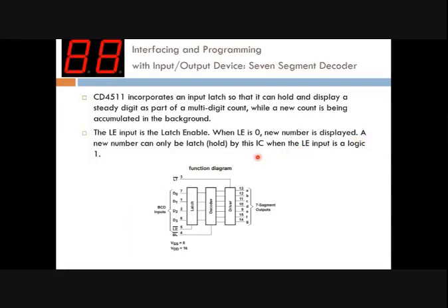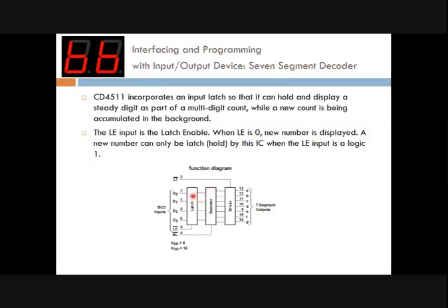After the updating process, you go back to giving LE 1 so that it can hold the value. So if the new value is 2, you turn on by giving 0, then the latch will update to number 2, and then to hold that value, you turn off again by giving 1.